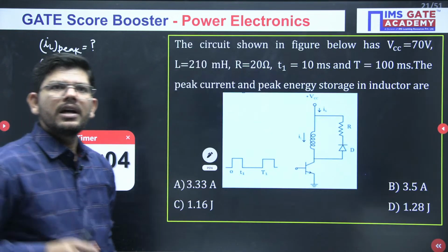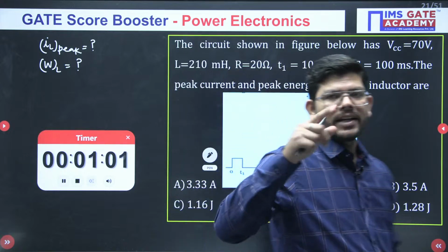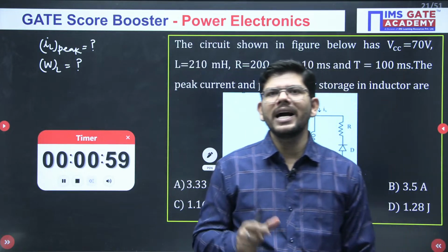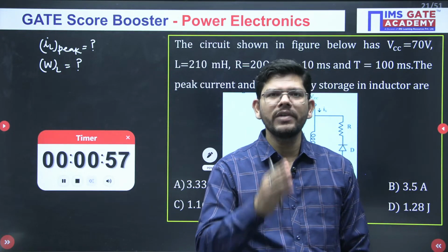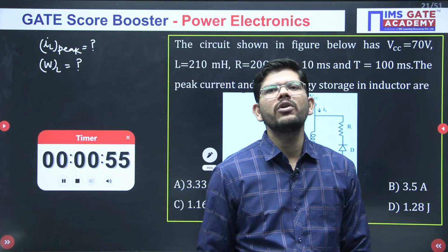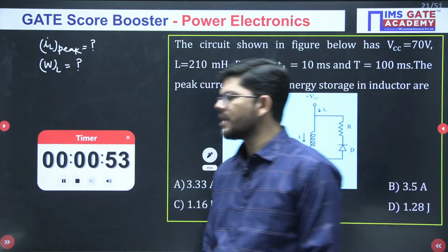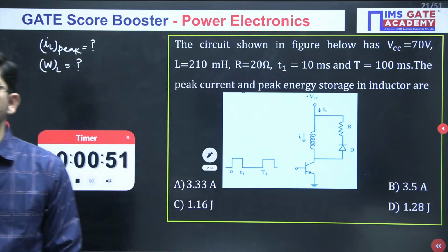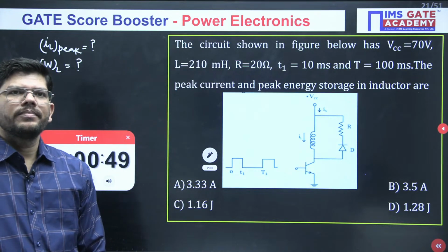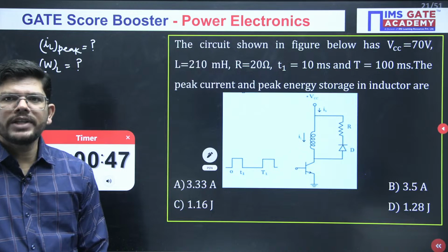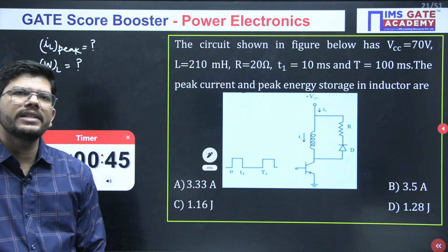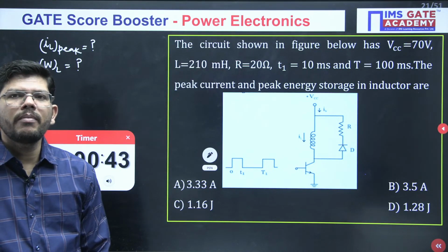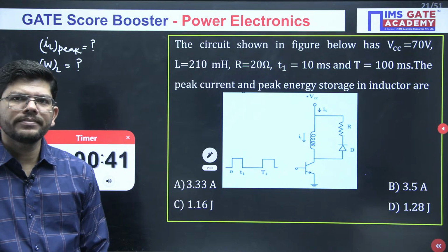It is not having that sinusoidal shape right now. IC is the current across the capacitor right now and it equals I naught current. So it is forced to become I naught. Focus on the waveforms that we have drawn. There you will understand that IC will become minus of I naught.